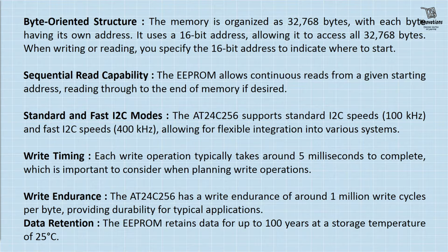Write endurance. The AT24C256 has a write endurance of around 1 million write cycles per byte, providing durability for typical applications. In the internal EEPROM of Arduino, we learned that it allows only 100,000 times of writing, but in this AT24C256, it allows 1 million write cycles. Data retention. The EEPROM retains data for up to 100 years at a storage temperature of 25 degrees centigrade, whereas in the internal EEPROM of Arduino, it was only 10 years of data retention.